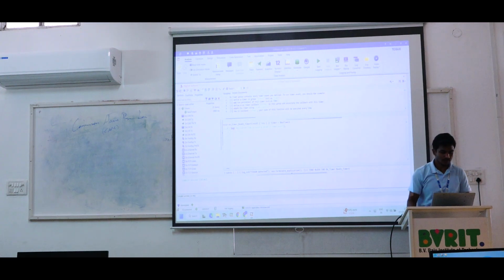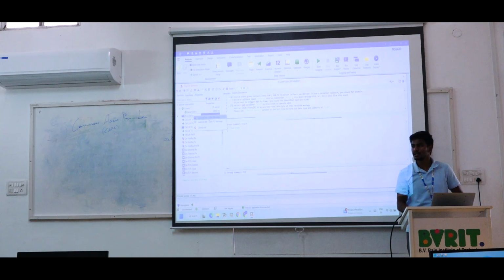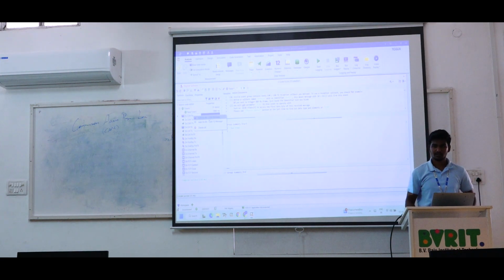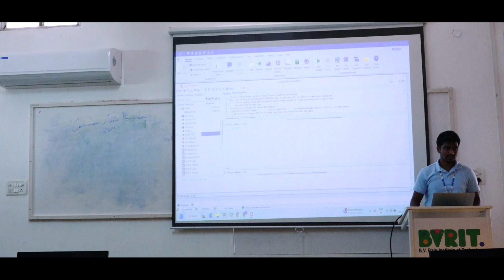Go to this on CAN RX. Right click. It is asking for on CAN RX, CAN message or FD message. We are working with classical CAN, so open the CAN message, the first option. Once again I repeat: on CAN RX, right click. It is showing the two options, CAN message and FD message.